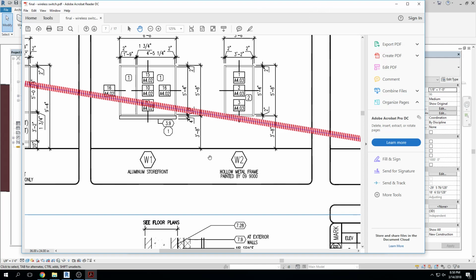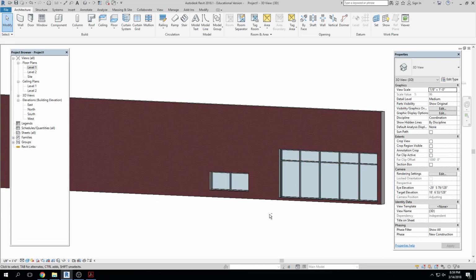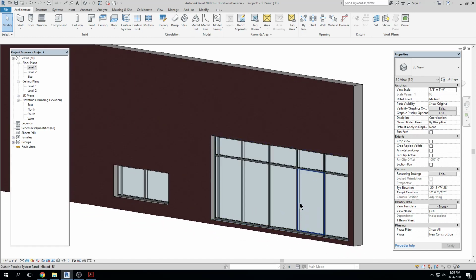So when you would go to generate this in Revit, you would give the window a base offset of 3'8" from whatever level you were drawing it on, an unconnected height of 5'8", right? And then you go to a floor plan view and you would draw the length of it, whatever those are. Oh, 6'8" added up. Okay. So that is an easy way to do it. The windows are not terrible to draw, right? They make sense. They're like walls, essentially. Okay. Any questions so far?